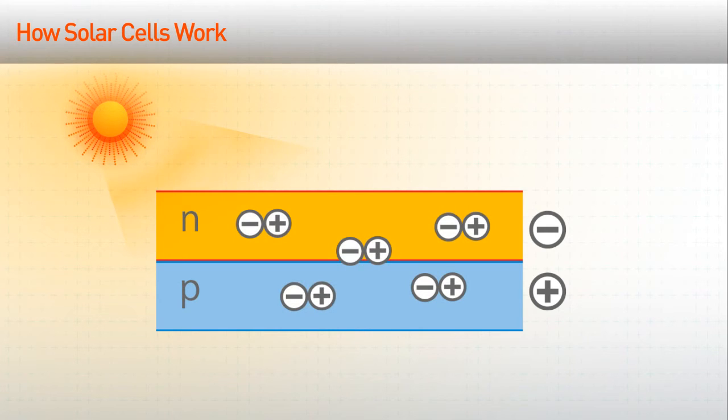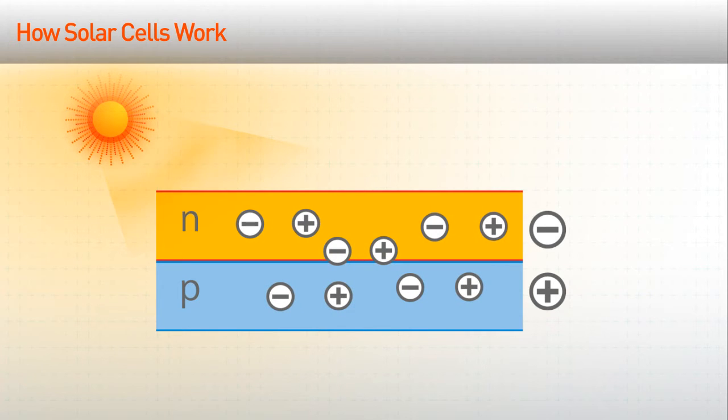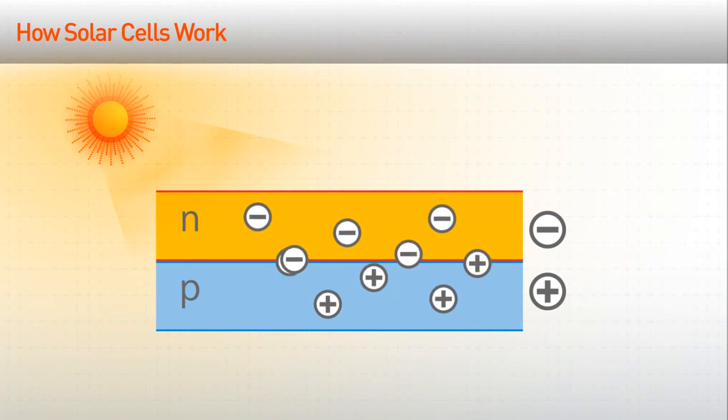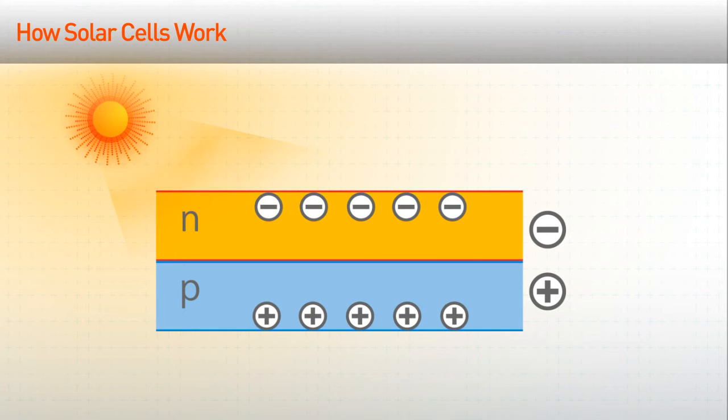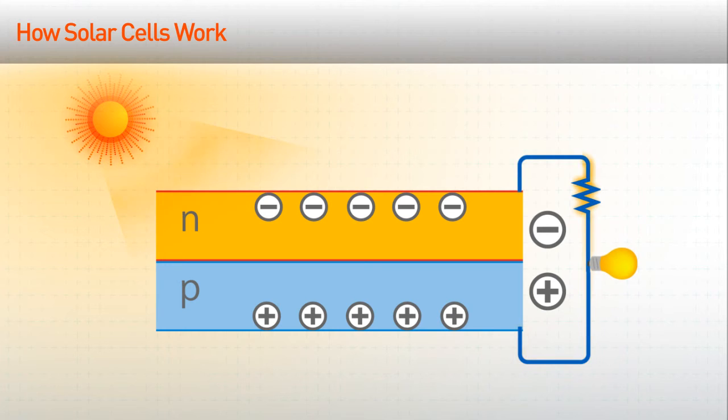When sunlight shines on the solar cells, the photon energy excites the electrons in the semiconductor material to produce electron-hole pairs. The electron-hole pairs are subject to the internal electric field formed by the p-n structures in the solar cells and then driven to separate. This causes electrons to move to the negative electrodes, while the holes move to the positive electrodes. Finally, the positive electrodes, the negative electrodes, and the loads in a series are connected by conducting wires to form circuits. As a result, electric currents are generated to supply external loads.